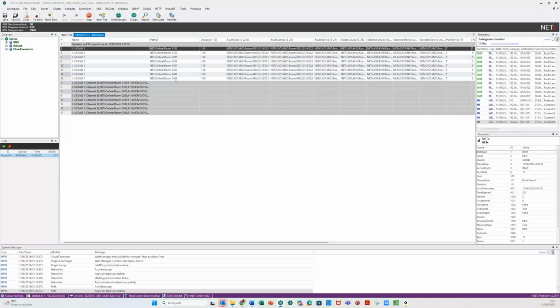But the most important thing in this table is this. By default, you only have a polling of the first 10 devices in your driver. So if it's not the case, and it will not be the case because 1 to 10 is just a casualty, you have to change it. For example, imagine that our DALI gateway only considers 1 to 3.